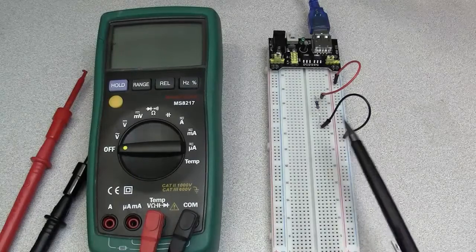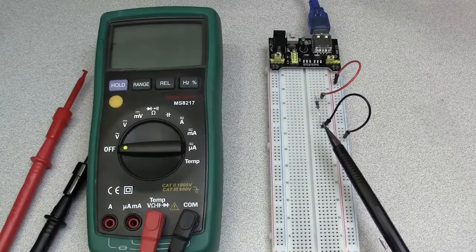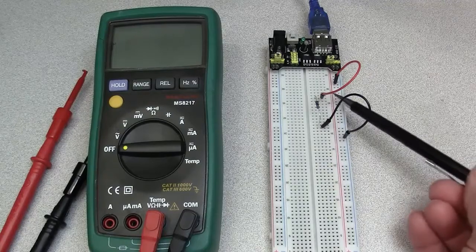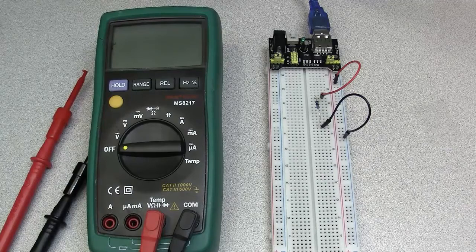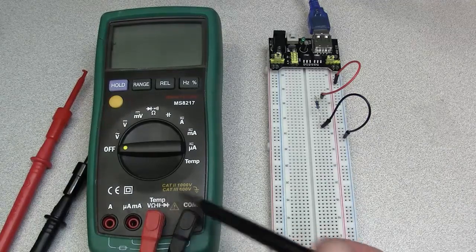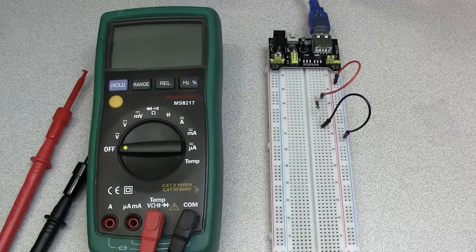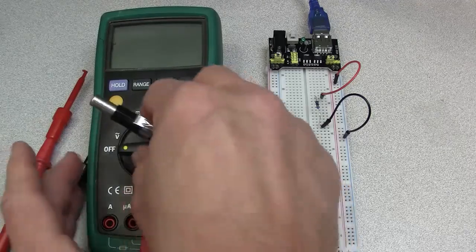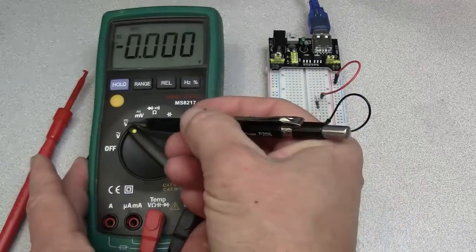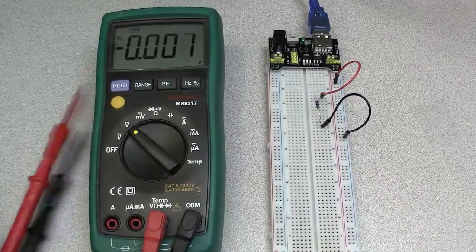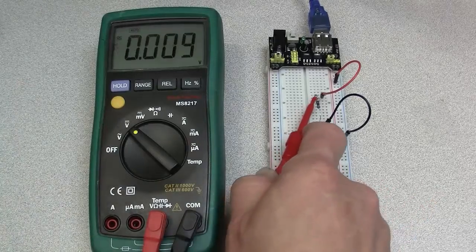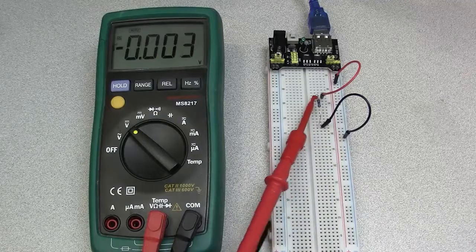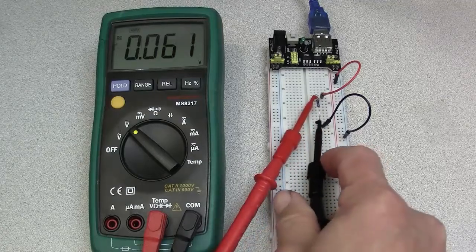This is the really simple circuit I'm going to use to estimate resistance. I've simply applied 5 volts across this resistor. First, I'll measure the voltage across the resistor by plugging the DMM leads into the volt-ohm ports and the COM ports. The function selector is set to V with a bar over it. Now I can just connect the leads across the resistor, the positive lead at this end and the negative lead at this terminal.